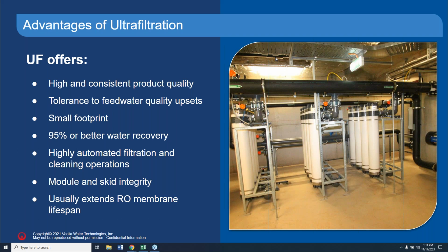The cleaning operations are very easily automated, and it does not take a lot of labor to operate. The other thing is that when you operate one of these, they're very easy to troubleshoot. You can look at the integrity of the membranes and know if you have broken fibers or whatever, and address those very easily on site without having to call in specialty providers.